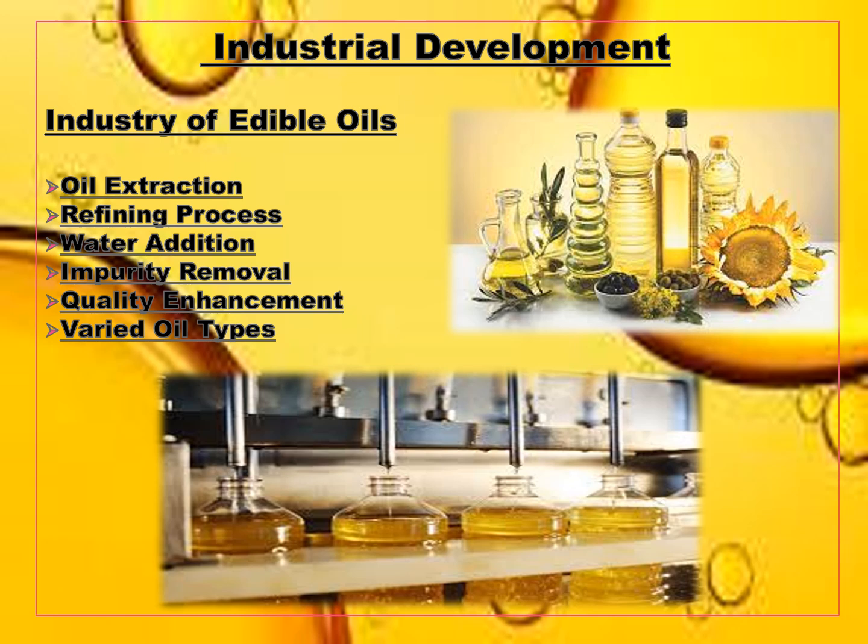The refining process involves heating the extracted oil under vacuum conditions, approaching its smoking point. The controlled heating helps remove impurities and undesirable flavors and odors. Water is introduced at the bottom level during the refining process. The heat causes the water to convert into steam, which bubbles through the oil, and the steam carries away water-soluble chemicals, aiding in the removal of impurities.